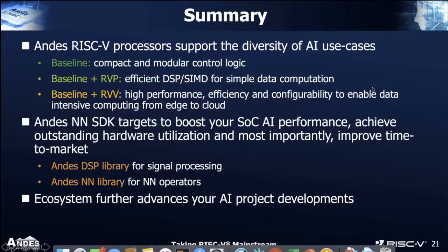It's functionality wise. Right now, on the higher end processor, the vector unit is not small. One typical implementation with 512-bit vector length, with the full processor and the memory, we're targeting about 3 square millimeters in 7 nanometer technology. That would be the very high end of the vector processor.